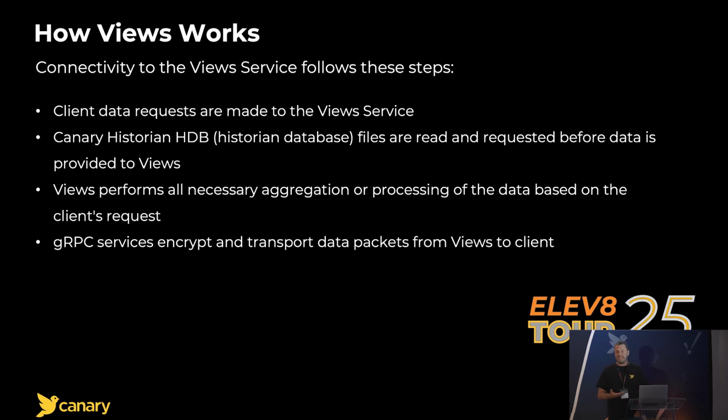So the Views is really the gatekeeper for all data. So any requests, as Kyle said, are coming through Views. It actually does a lot of the hard calculations that we do too. So when you make a request, maybe you just want the raw data. That's easy. That's a straight pass-through. Maybe you want what we call processed or aggregated data. Instead of having to have another historical tag that is your 1 hour average, Views can actually do that computation on the fly. So you can make a request for a set of tags over the last month, what's my 1 day average, and Views does all that quick computation and spits out the result.